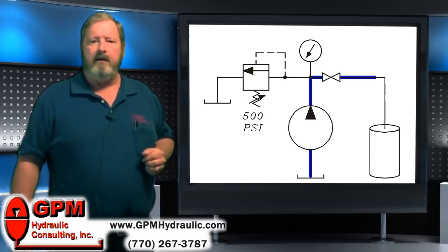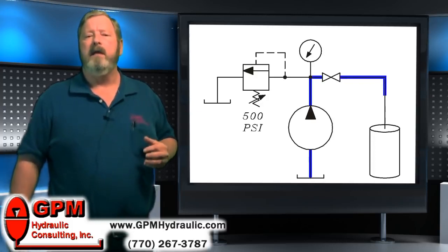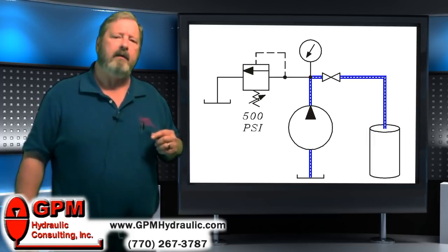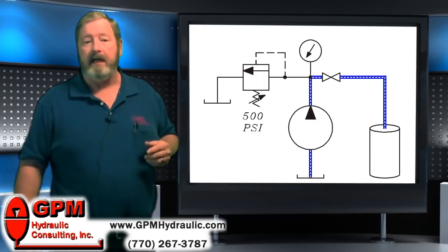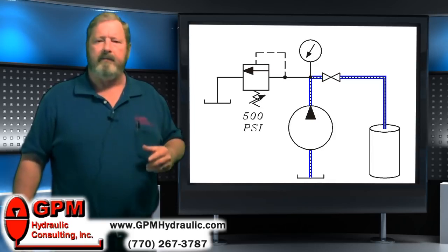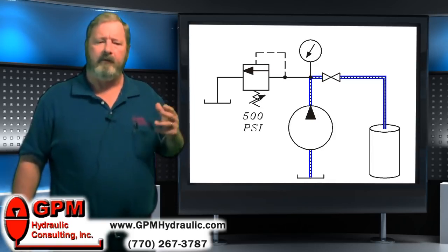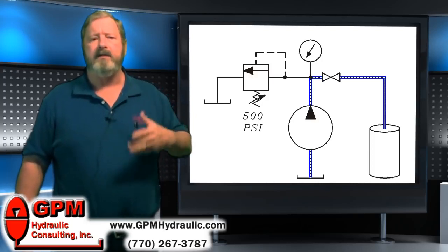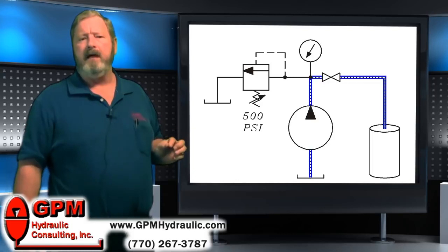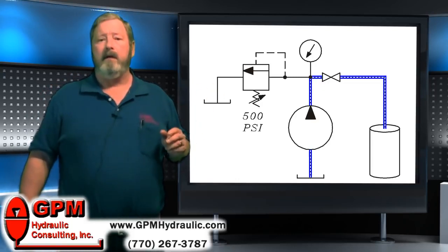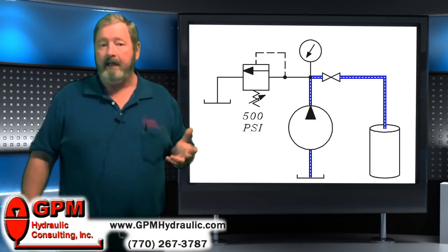So we turn the pump on, the oil goes into the oil drum, and what pressure do we read on the gauge? Well, if you said 0, you're right again. There is a little bit of resistance with the friction of the pipes, overcoming gravity and whatnot, but for all practical purposes, there is no resistance, and the gauge would read 0. So does that mean that I need to change my pump? Well, of course not. A brand new pump would perform exactly the same way, would it not?